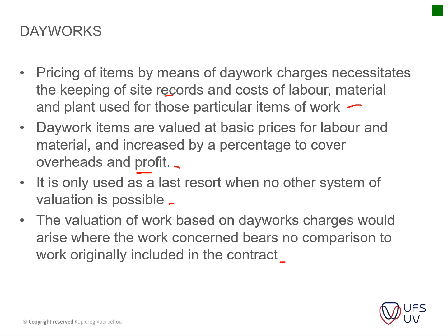So in short, if you do not have rates or other items measured for those items, then it would be best to use day works, and then only day works will kick in. If you have rates that you can use, it's easier and better to use bill rates for items completed. So it's best to have a completed item measured than reverting back to day works where you have to measure time and output and so on.